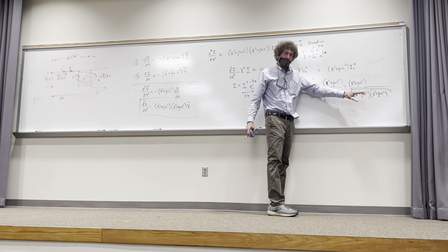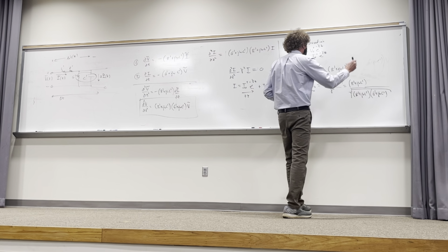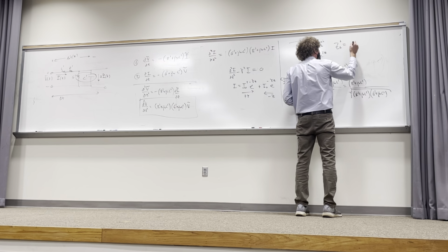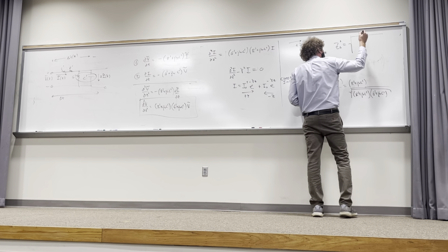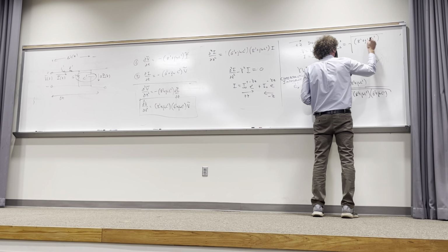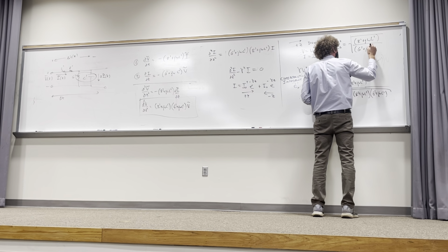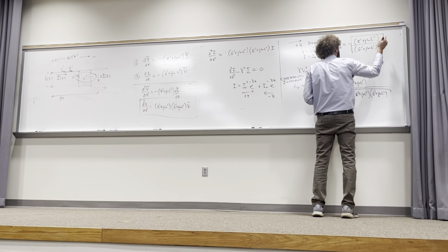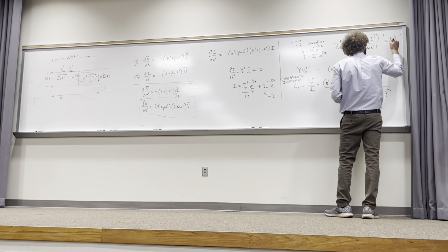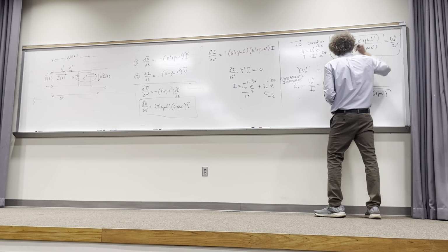So that means in the final result, when you divide that out, you end up with, and I'll put it right here, Z0 plus equal to the square root of R prime plus j omega L prime over G prime plus j omega C prime. And that is the ratio of V0 plus to I0 plus. And that's important. That's called the characteristic impedance.